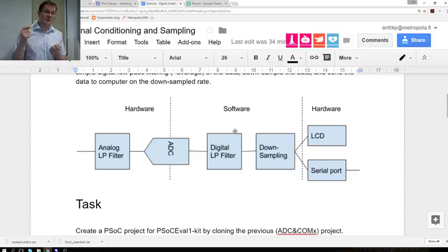For example, if you are making measurements of AC power, you are measuring voltage and current at a higher rate to calculate the power, and the power has meaning only within, say, a 1 second time frame.